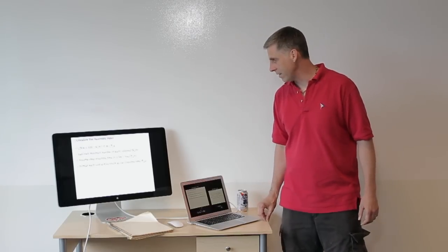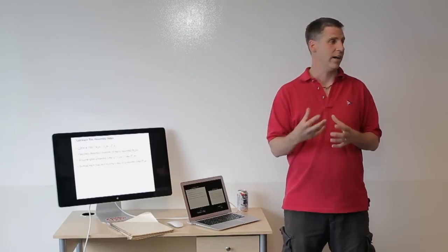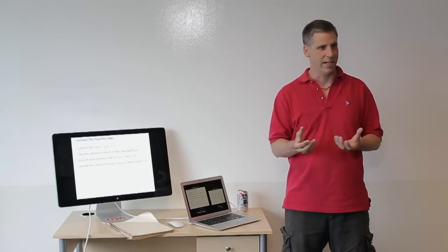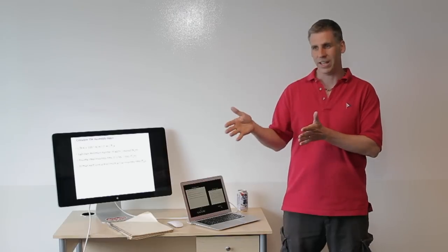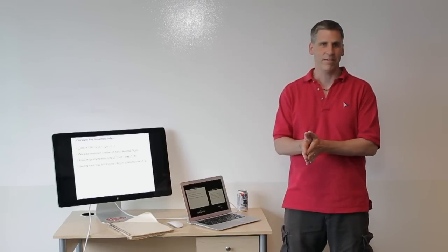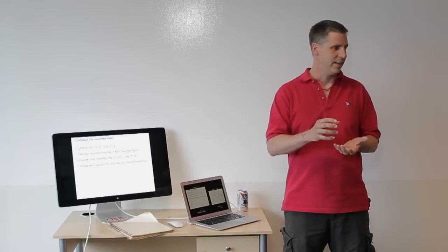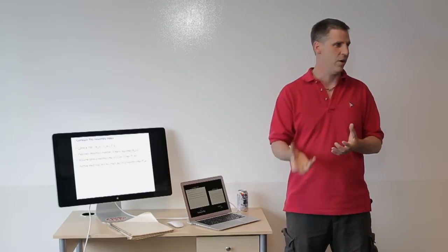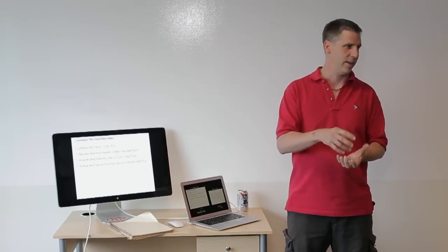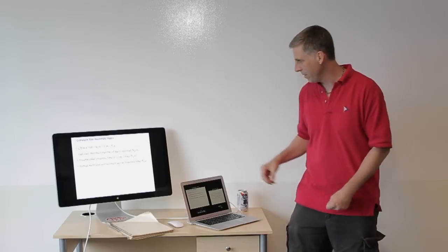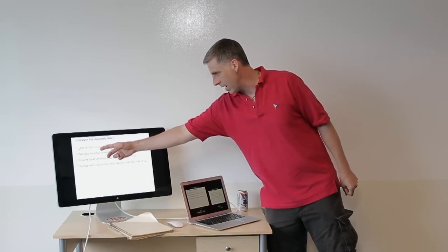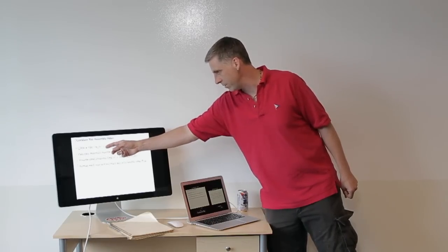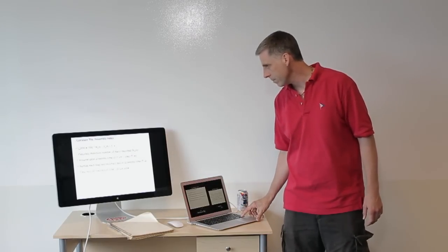And then you want to calculate actually how long does it take to put together your thing. And in that case, you take your product and literally start the stopwatch, put it together, and see how long it takes. If you didn't have the thing in front of you, say it was all designed in CAD, then you can do the mental experiment saying, oh, I think it's going to take 4 seconds to do this and 5 seconds to do this, and add it up. And then basically you just multiply the minimum number of parts you calculated times 3 seconds each, and then divide it by the actual time.